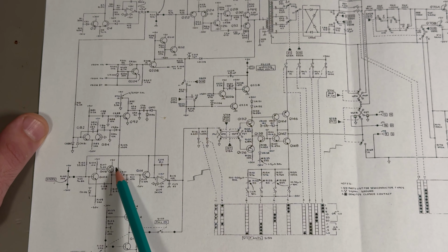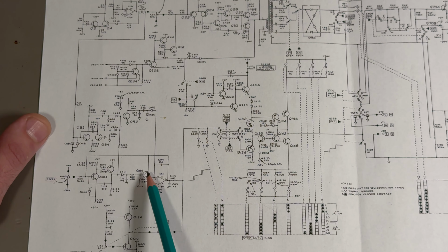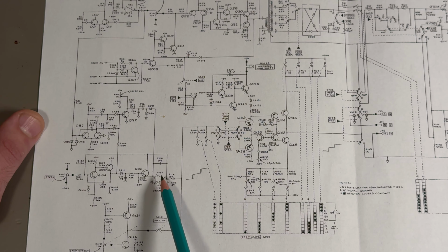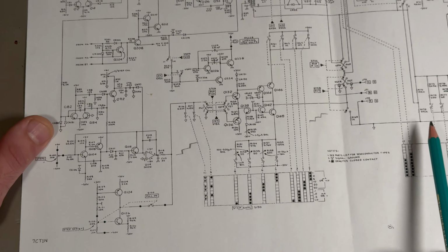It turns it off, and that pulse also goes through CR111, the capacitor and this resistor, and turns this thing on briefly. And you can see it's across this capacitor basically, and it just resets the integration capacitor, so it brings it back down to 0.